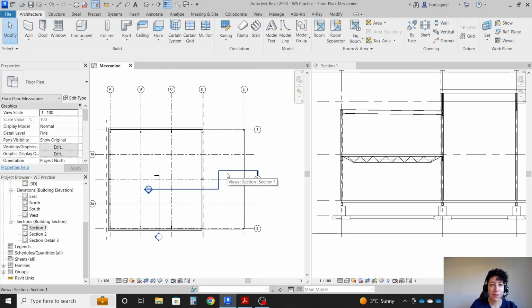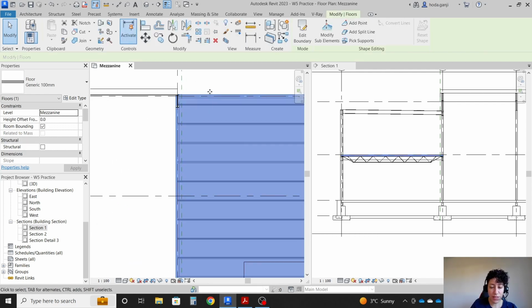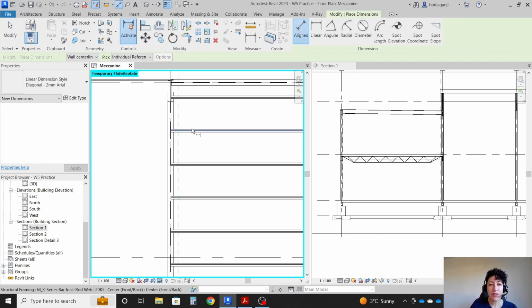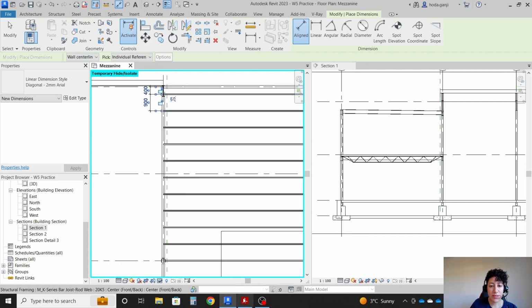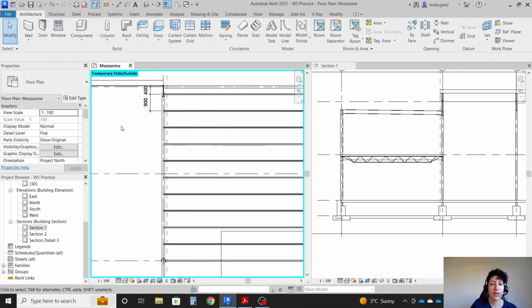So in my mezzanine level, how about I click on the floor, HH, hide it temporarily, DI, and from there to there to there, it's exactly how we see in the view here. So that's good. Okay, so then we can continue with the roof level.